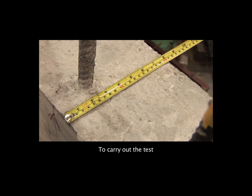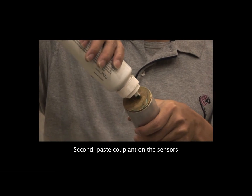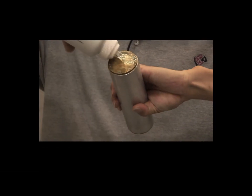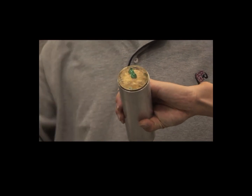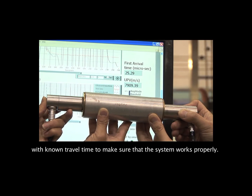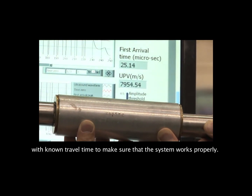To carry out the test, first we measure the physical distance on the surface of the concrete. Second, place couplant on the sensors. Calibrate the probe using a steel tube with known travel time to make sure that the system works properly.